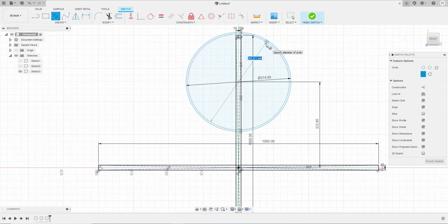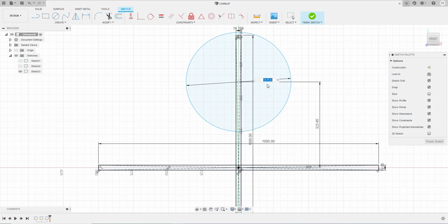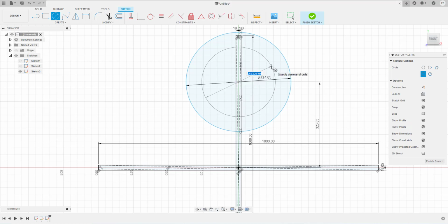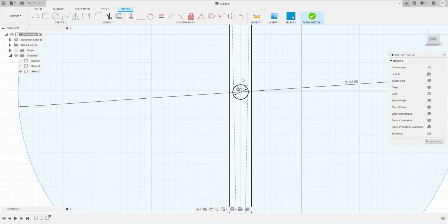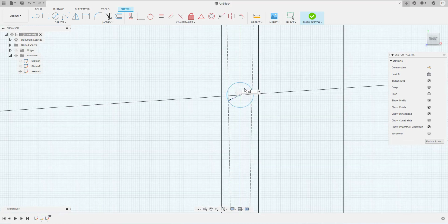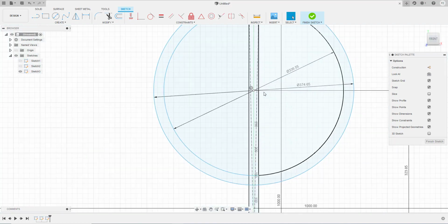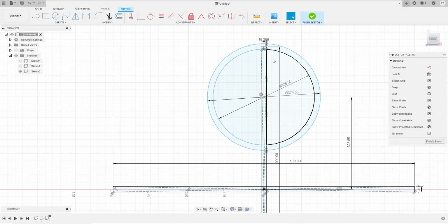Okay, and now we're going to draw in the interior of this design. And we need to make sure that this is 0.75 inches across. So if the outer ring was 14.75 and we draw another one, we need to make sure that on each end we get that same amount. So I'm going to subtract 0.75, but then I'm going to do that twice. So this is going to be 13.25 inches. So this circle is going to be 13.25 inches. Enter. And you see what happens if you don't type in the unit, you get millimeters.